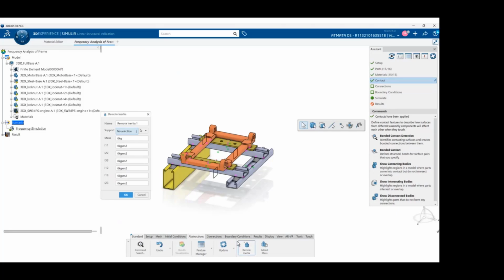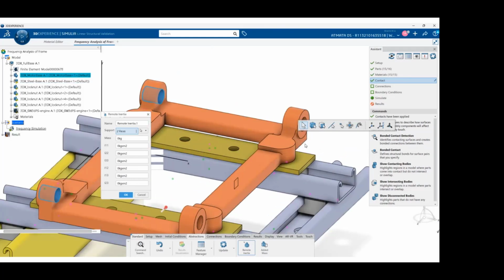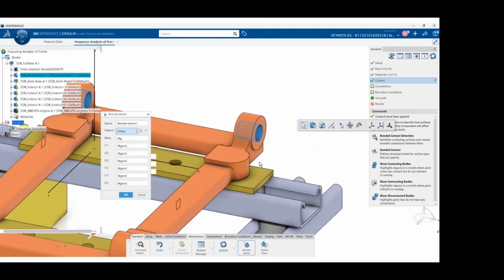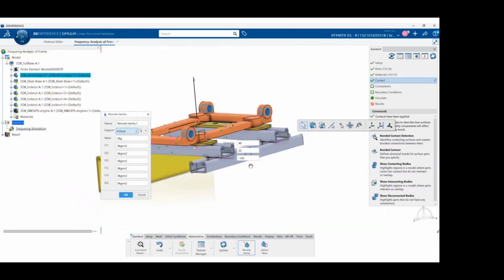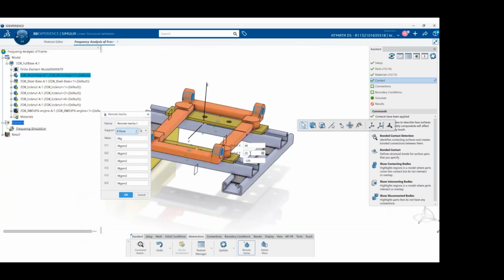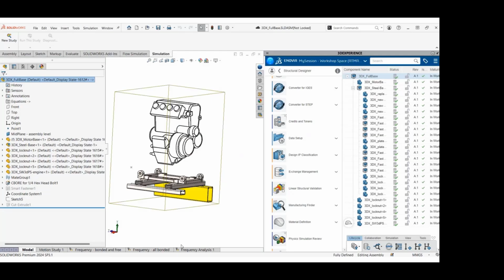Next I am going to the remote inertia. Here it is not a remote mass; this is called a remote inertia. I will choose the location where the body was fixed. Now I have to give these inputs: the mass and the inertia in XX. Here 1 refers to X, 2 refers to Y, 3 refers to Z, so IXX, IYY, IZZ. So how do I get these values?